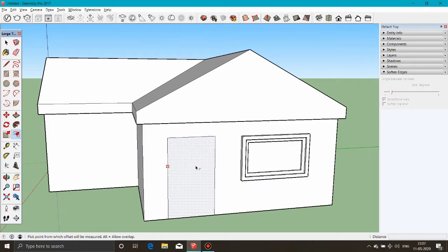Use the Select tool to select one door edge, then, holding the Shift key, add the other two edges. With these edges selected, the Offset tool will focus and only work on those edges, so we don't have any problematic edges below our house and can correctly create the door frame. Pull the door frame out so we can use it in our next example.